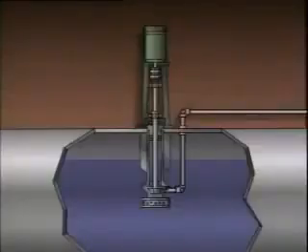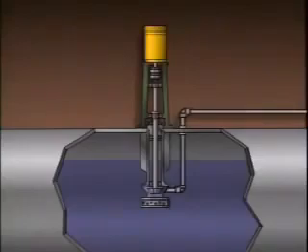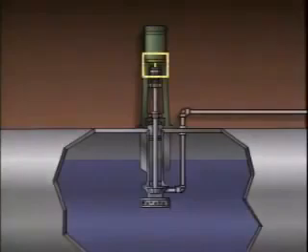In some installations, it's often necessary to keep a pump's driver above the liquid while the pump is submerged in the liquid. One type of centrifugal pump that you may find in these applications is a vertically mounted centrifugal pump. We'll use this illustration of a vertically mounted centrifugal pump and its driver to see how this type of pump works. The pump itself is submerged in a tank containing the liquid being pumped. The driver, which is an electric motor, is mounted above the pump on top of the tank. Its shaft is connected to the pump shaft by a coupling.